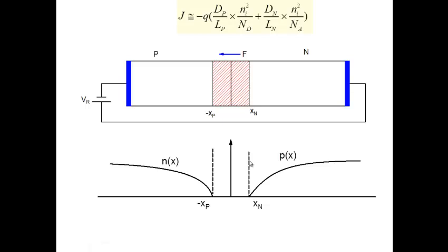The generation process here is the reverse here. So what is happening is, let's look at this process. Let's look at a region roughly a diffusion length from here and a diffusion length from here. A qualitative concept of diffusion length that you should keep in mind is the average distance a hole travels before recombining. So if you create excess holes here, for example, let's say this region is the extent of the diffusion length.